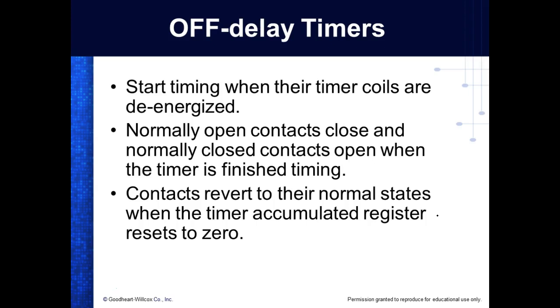Right? You understand? Good. But when you're inside the PLC, so if I'm using a contact that comes from even an output coil, if I'm using a contact down here, which is considered to be an input, right? You understand that? Even though it's controlled by a coil, it's still considered to be an input or a control device. If that coil is true or energized, that normally open contact will be what? Closed. If it's false, a normally open contact would be what?